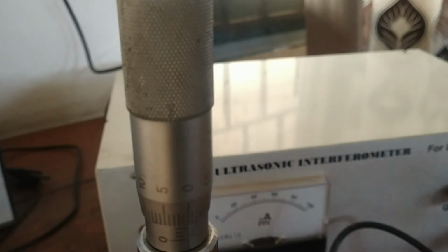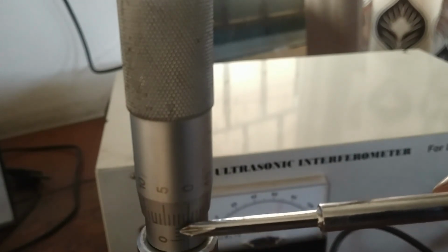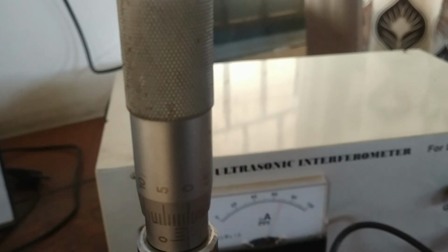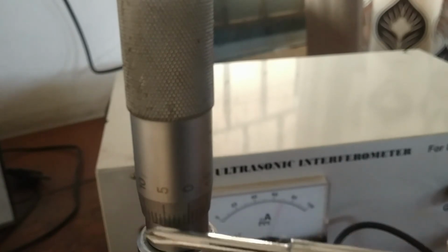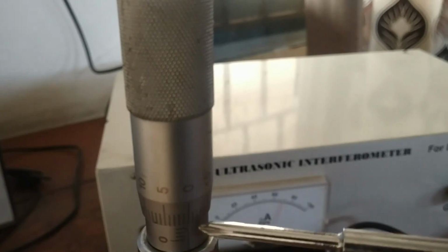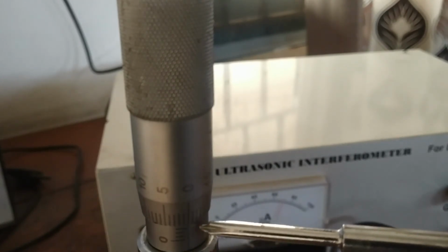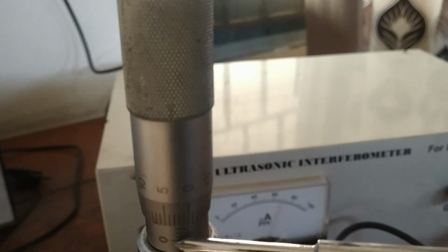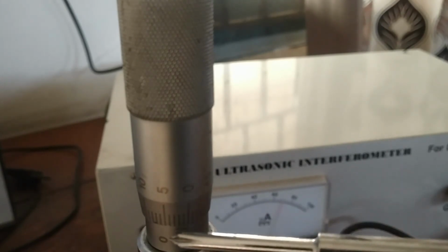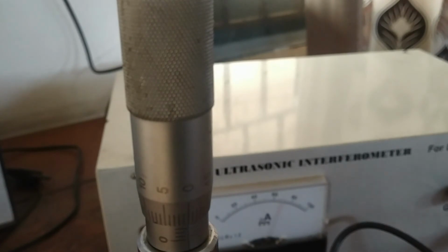So this is our 0 of the circular scale and this is the reference line of the main scale. This is 0, 1, 2, 3, 4, 5, and on this side I will show it later. This is the reference line. To the left of the reference line we have integer divisions. To the right of this reference line on the main scale we have half integers. Actually 0 is here, 0.5 will be on this side, 1 will be on this side, 1.5 on this side, 2 on this side, 2.5 on this side. So I will show you later on.